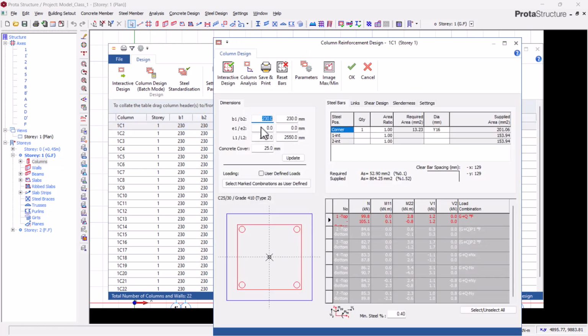In case your utilization ratio is not enough, you can choose to increase the size of your reinforcements, or you can choose to increase the quantity. You can choose to add more reinforcements. If you come here and you type 1, you see it will increase, it will add another reinforcement. It will add another y16 by this side. And if you come here and you type 1 here as well, it will also bring out another layer on this other part. So you see,